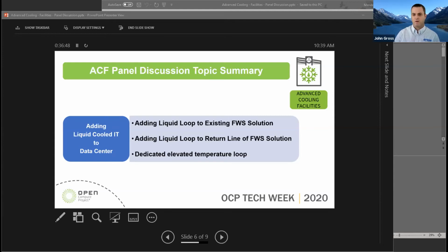When we're thinking about ITE and we're thinking about data centers, we think about a CDU as a heat exchanger, a chiller as a heat exchanger, a cold plate as a heat exchanger. Well, the case of the processor is also a heat exchanger. And a lot of the processor manufacturers and chip manufacturers are starting to run into issues with getting the heat flux across that case temperature, because the case temperature is what's getting affected by the immersion solution.